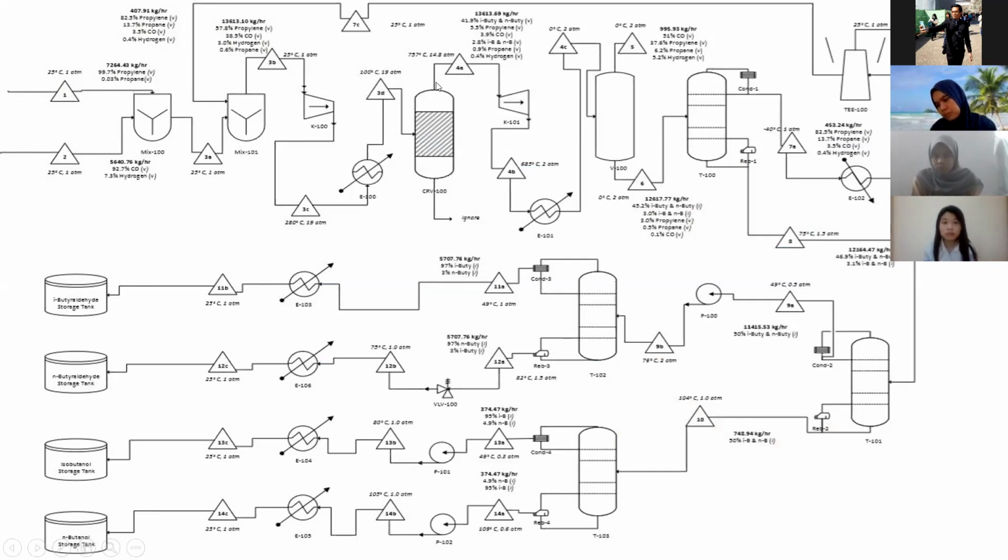Let's move on to the gas outlet stream of the reactor. The gas outlet stream has two extra side products, which are isobutanol and N-butanol. This gas outlet stream will be sent to a flash drum to completely separate the vapor stream and the liquid stream. To match the operating condition of the flash drum at 0 degrees C and 2 atm, the gas outlet stream of the reactor will undergo temperature and pressure changes via a turbo expander and a cooler. The vapor stream of the flash drum will be treated as waste gas, while the liquid stream will be fed to a distillation column to minimize the impurities that shouldn't enter the further separation process below.